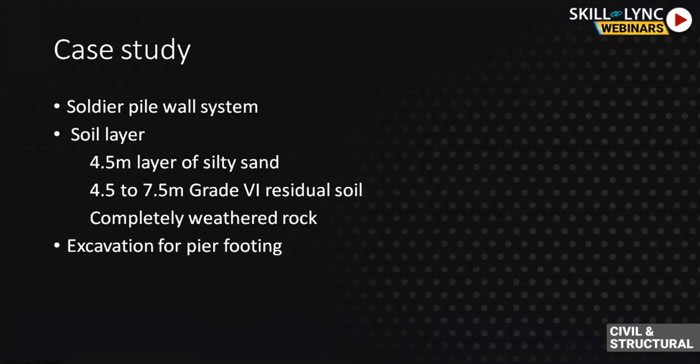For this type of excavation, I'm just saying how we can select a wall. This is a temporary excavation, so we have to go either for a soldier pile wall or a sheet pile wall. We cannot go for a diaphragm wall for a smaller shoring system. And for the secant pile or contiguous pile wall, you need boring rigs and equipment for boring in those cases.